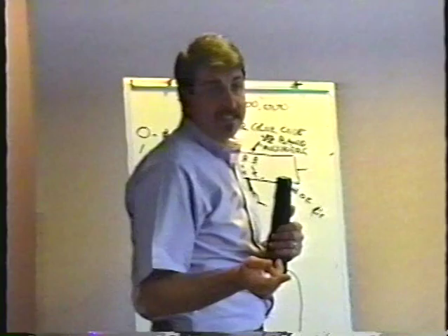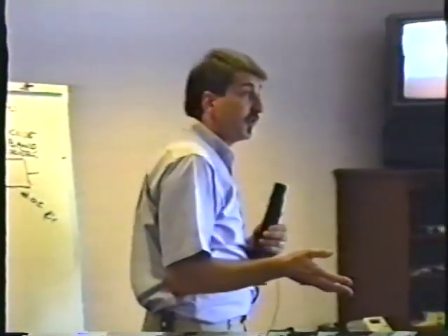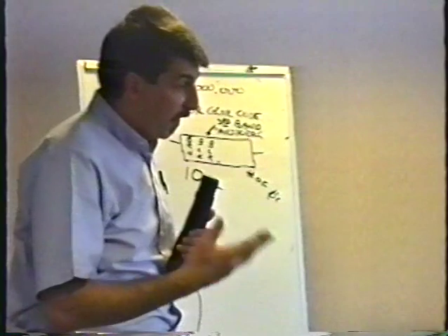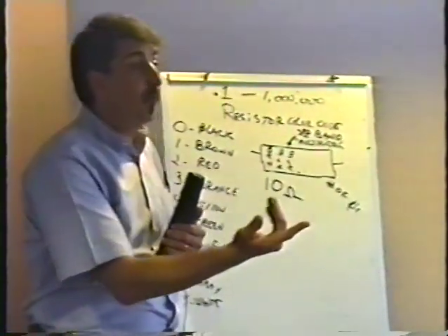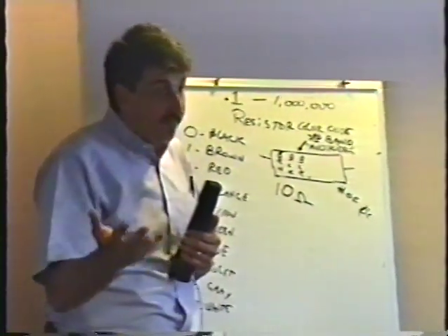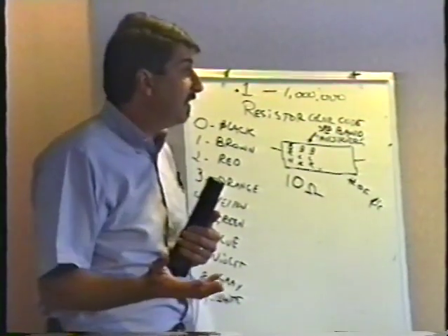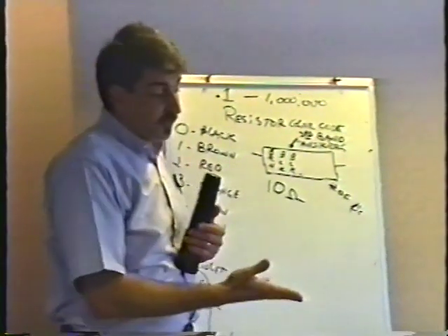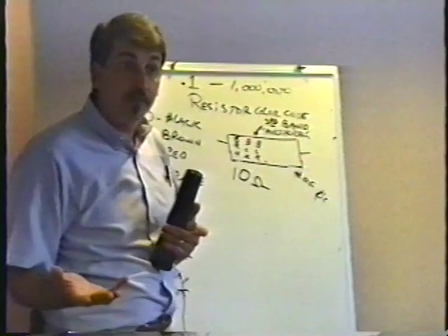You go ahead and replace that 10 ohm resistor with the 100 ohm resistor. Obviously, when you turn the thing back on, it doesn't fix anything, does it? Because you not only changed a good part, but you've changed it with a part that's the wrong value, right? You made it worse because even if you eventually find which part is actually bad, you may never get it to work because this new resistor you put in there is 10 times the value it should be.